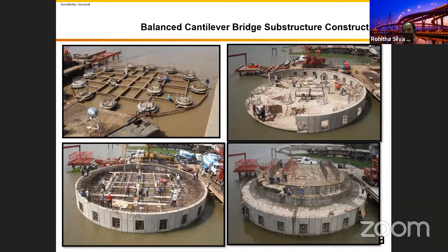You are designing this bridge, you get the load, you put everything in there, you build this bridge, but the construction staging plays a massive role when you are building this bridge. You can see these piles. It's a 2 meter diameter pile, 3 meters in length. I could remember, for the one end of the piers we have on the east and west, the river bed is about 17 to 18 meters below. The other one is a bit shallower than that.